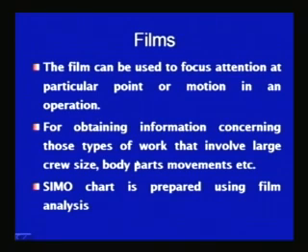The films are also used for developing the SIMO charts, which are also known as simultaneous motion charts. Using the film, micro motion films are made and those are analyzed one by one, frame by frame, to see what is being done at the different movements, and those activities are recorded in the SIMO chart for seeing and analyzing the jobs which are of very short cycles.